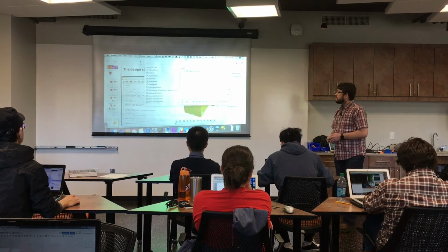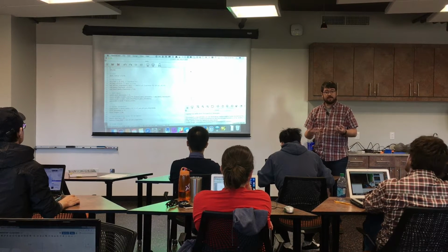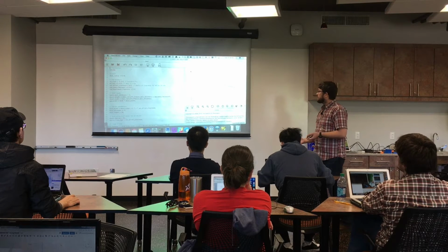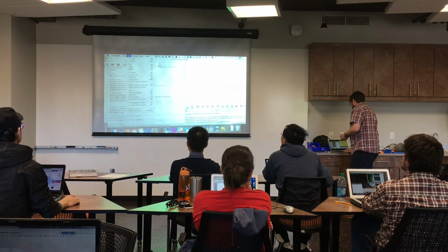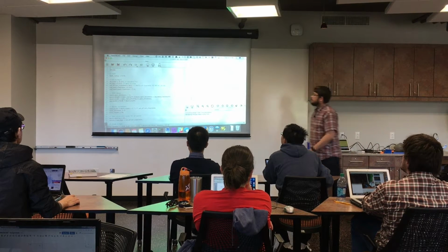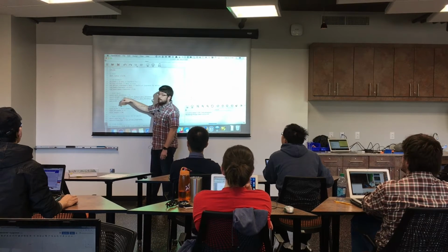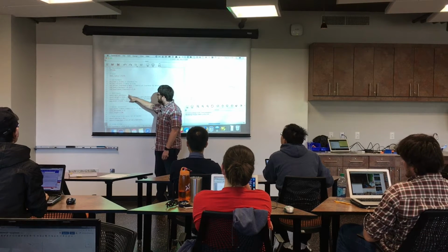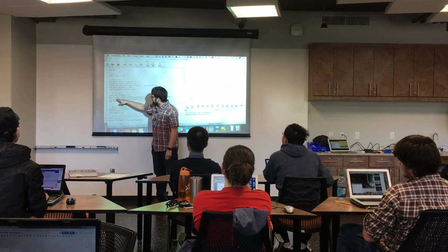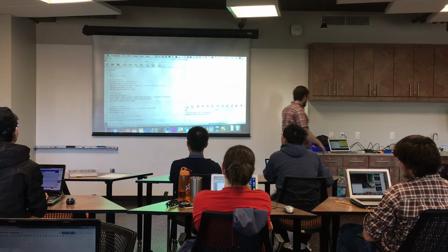So we'll open it up here. It's really nice because you can create variables for, say, a part width or spacing between holes or hole sizes, and then you can change them and the part will change. So let me render this design here. As you can see, I have M3 clear, M3 tap, so metric 3 clear and tap hole sizes, some clearances, how thick I want the wall to be, how wide, all of these different parameters that I could change.